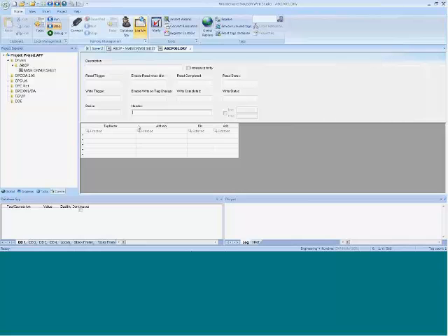For example, I went to a customer site one time and they said, hey, my communications is too slow. Well, they were reading in thousands of part names every time the machine ran. And I said, well, do you need to do that every time? They said, no, we only need to do that once a day. So we moved all of that out to a standard driver sheet and triggered that once per day whenever the database updated, and that fixed their entire problem. So it was more of a development and design issue than a slow driver or anything.